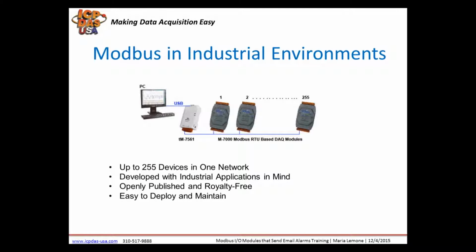Modbus is a serial-based communications protocol that's widely used in industrial automation. Modbus allows for communication between many devices connected to the same RS-485 network. For example, a system that measures temperature and humidity and communicates the results to a computer. Modbus is often used to connect a supervisory computer with a remote terminal unit, RTU, in supervisory control and data acquisition systems.